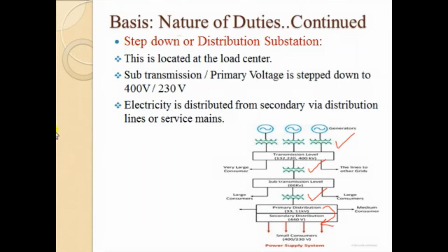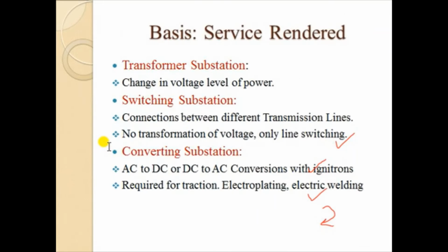But there are some other functions of substations also. Depending upon what type of service is being rendered by the substation, they are classified as a transformer substation, a routine concept again, because they are changing the voltage level of power. But there are some substations which may not have a transformer. They are simply playing the role of switching transmission lines. So they play a very important role in protection systems, system isolation. They operate as junction points in the transmission system.